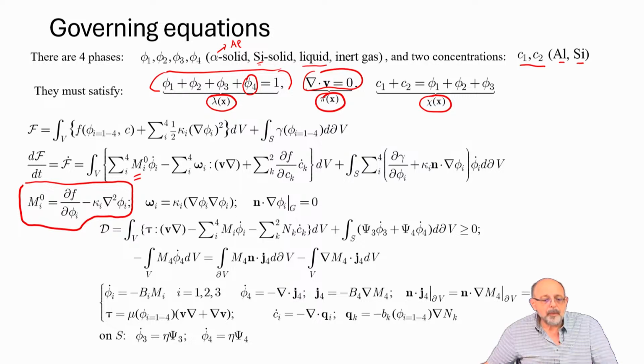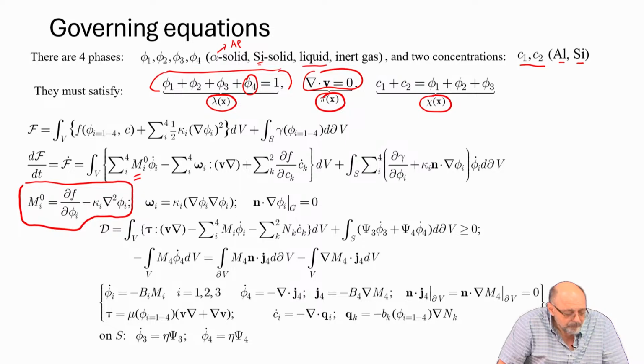Also, we ignore changes in volume and thermal strains, because there are no thermal stresses. There is no constraint, it's a fluid, it just flows. So the viscous stresses are important, elastic stresses are not important. So volume is the same as mass, mathematically.